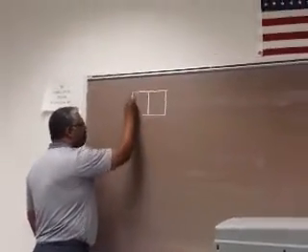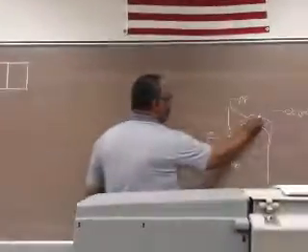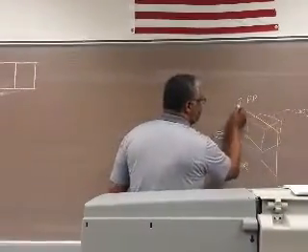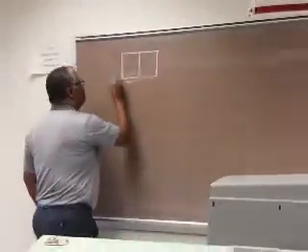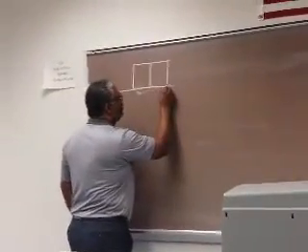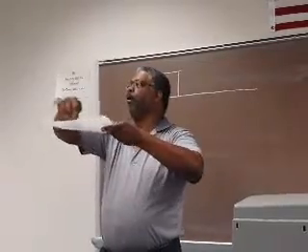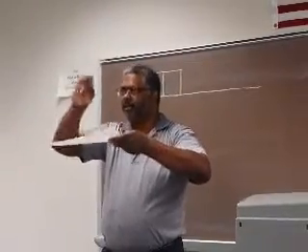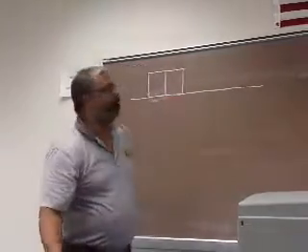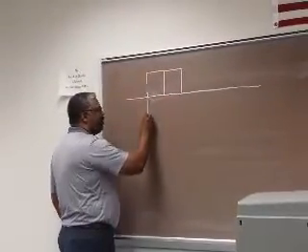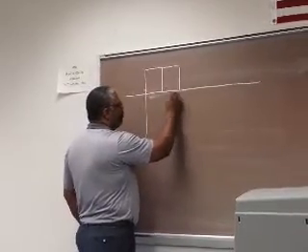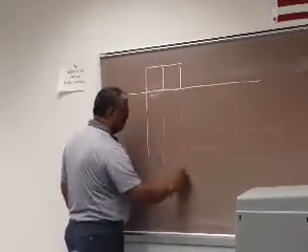and this is my top view, and this edge here represents my plane of projection. So this is my plane of projection. I have my object sitting on my plane of projection. Again, so that if I were to take a piece of paper and lay it on top of an object, I can trace that object at a 1-to-1 scale, because the piece of paper is directly on top of it. So that makes this front view of this object, at least this portion of the front view, 1-to-1.